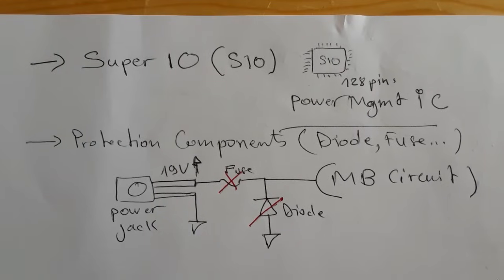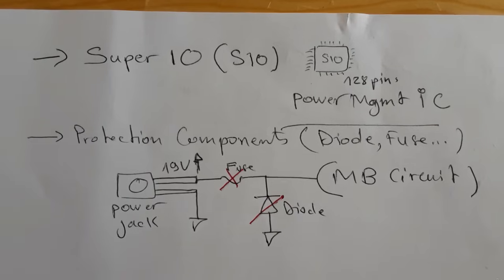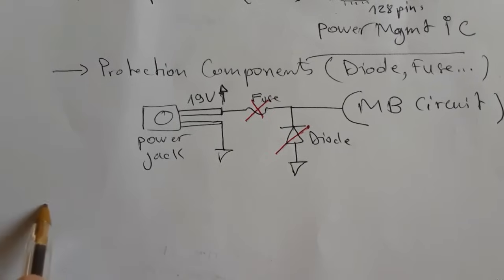That's why you should always check the protection component near the power jack when you get a dead motherboard or a failed motherboard.